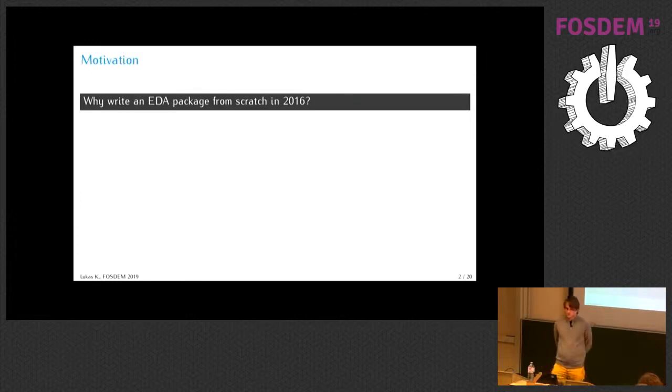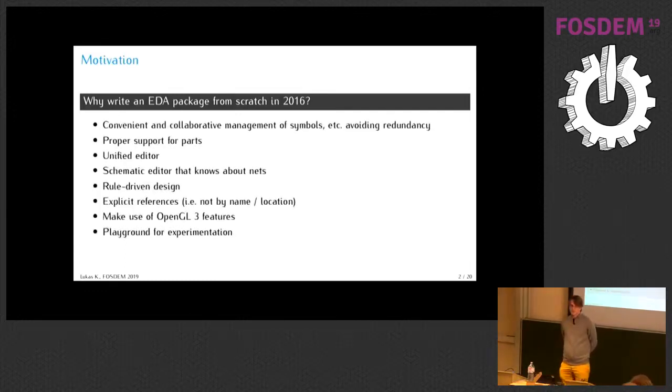So you might be wondering why that guy decided to write his own EDA package instead of contributing to something that's already existing. Some people say that a board can only be as good as the library of the parts, and to me that's also true for EDA packages. An EDA package can only be as good as the library data structure is, and I saw significant deficiencies in existing EDA packages in that regard. That was one of my main reasons for starting a new one, since, for example, in KiCad, the part definition is basically the symbol, the pins itself, and it also contains the pad names. And for me, that shouldn't be all in one thing.